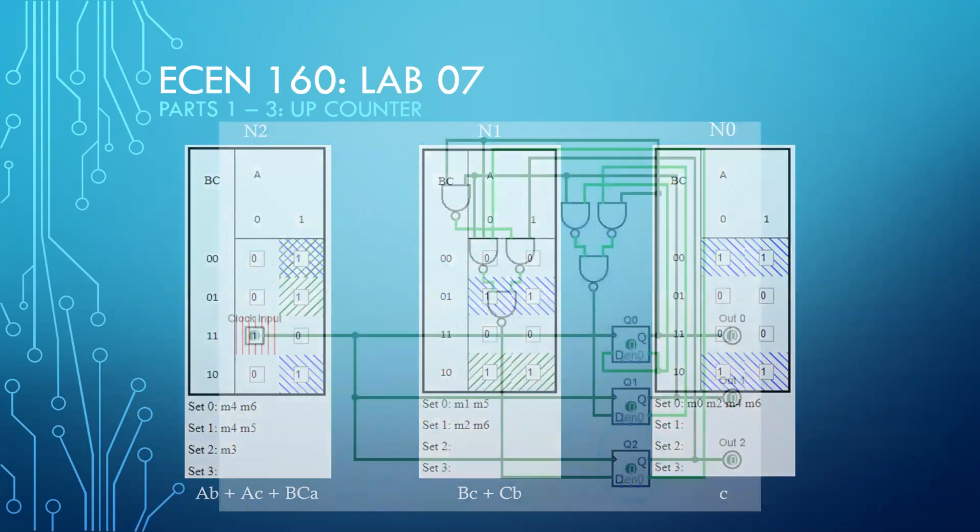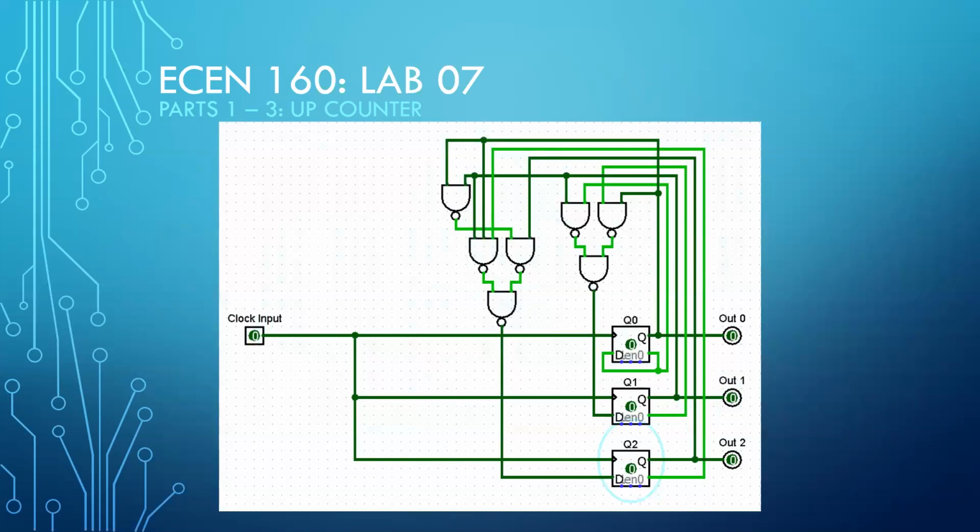The trickiest part of this was using only NAND gates. I was finally able to get it to work with the expected amount of NAND gates by using one 3-input NAND gate and 6 2-input NAND gates.